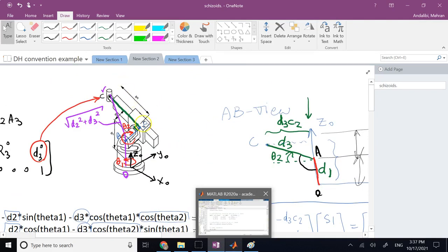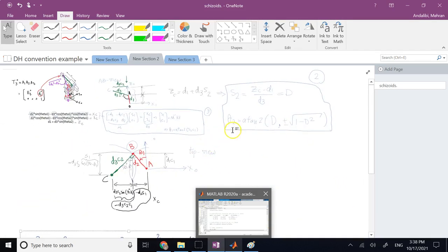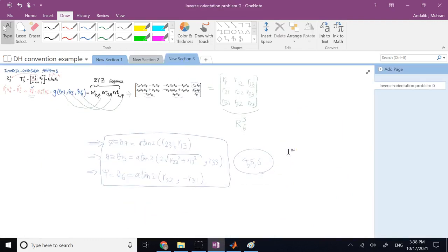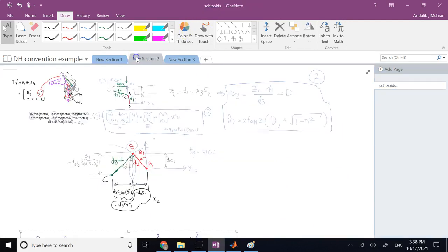Well, it depends on the mechanical limits. Typically, the prismatic joints, most of the time, move in a range that is not completely symmetric, negative and positive, right? They typically work in a positive range most of the time, but if that's the case, then you have 8 solutions. But here, at least you see there are 2 solutions for theta 2, 2 solutions for theta 5, so a minimal of 4 solutions. Although again, I said you could go up to 8 solutions in general.